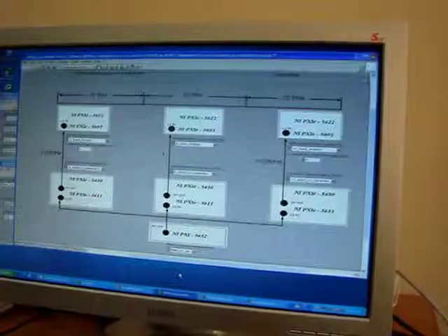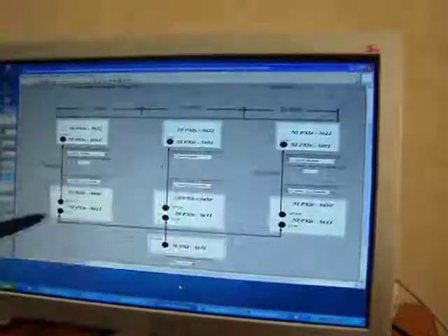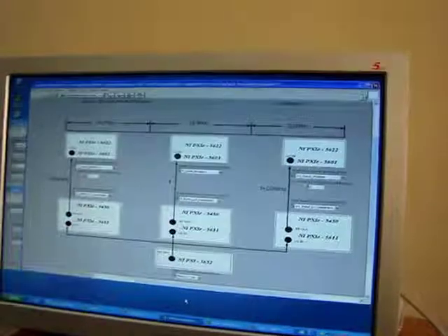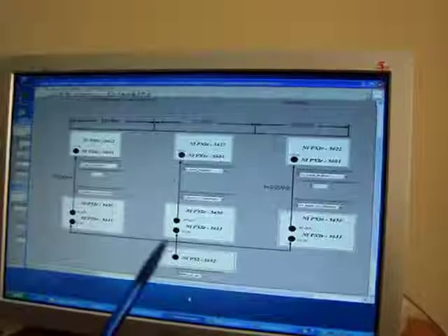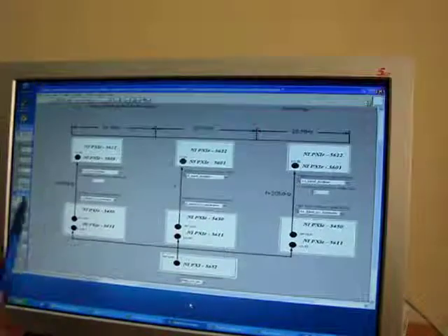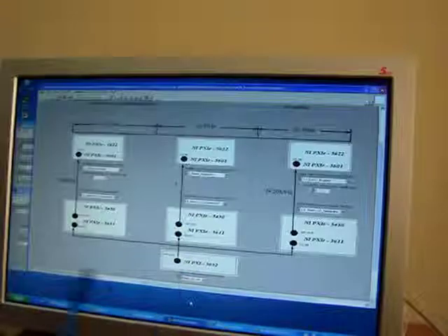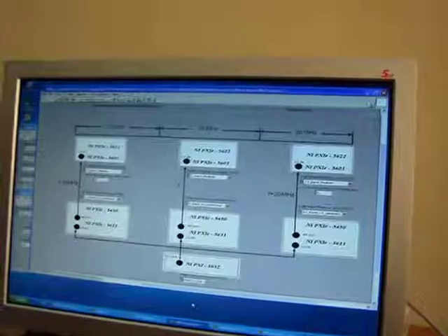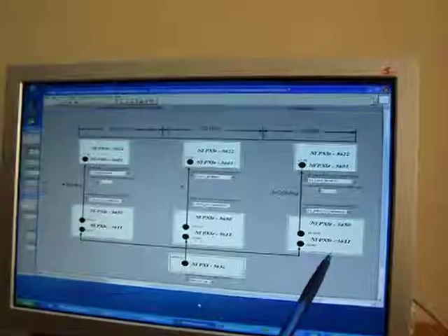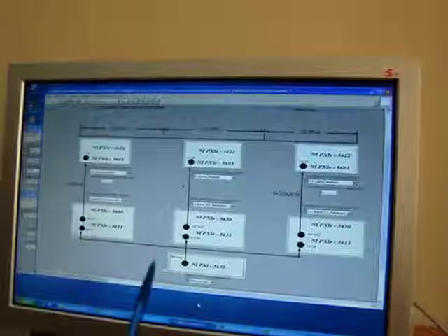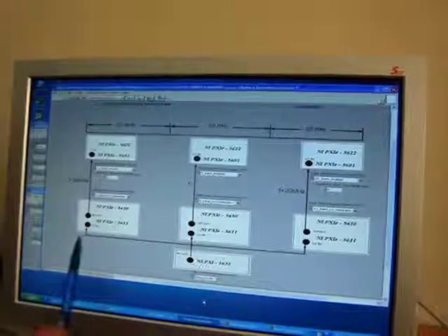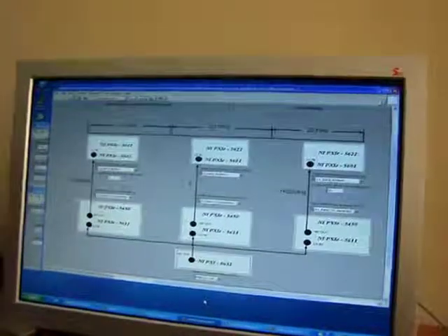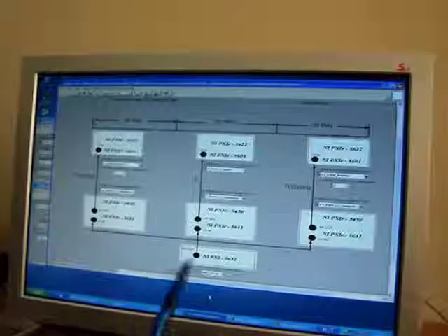For synchronization of these 3 vector signal analyzers, we needed 3 synchronized external LOs. That's why we get these LO signals from 3 vector signal generators with the same external LO signal, which is shared between each of them. For the concatenation, we use this one external LO, which gives a signal to the LO input of our 3 vector signal generators with the same sampling rate.